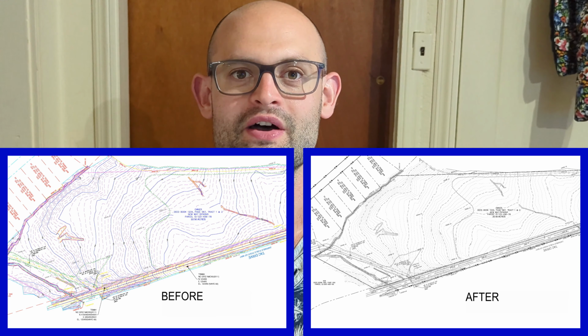First we had the unadulterated survey file. We made a copy of that, and with that copy, we opened it up and began our editing process. One of the first things we did is turned all the layers on, thawed everything, unisolated just to make sure we weren't missing anything.